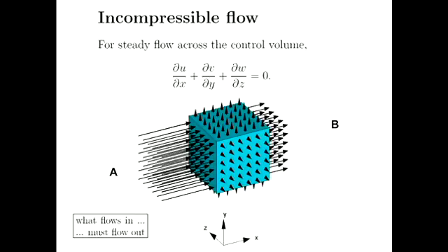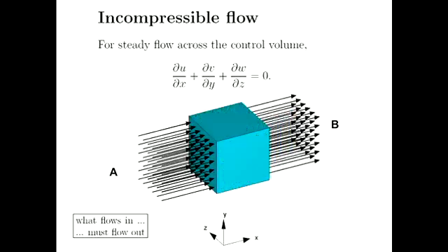For the second part of the course, when we start to deal with compressibility effects, weird things happen. In that case, if we back up and we've got this same scenario, stuff flowing in through A and stuff flowing out through B, when we've got compressibility effects, which remember could occur when we were moving very quickly in air and can't really occur at all in water. So if we're moving quickly in air and I then obstruct the flow coming out through control surface B, say with the nose cone of an aircraft, we've got this odd situation.